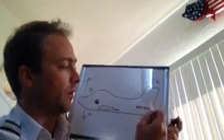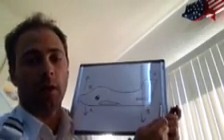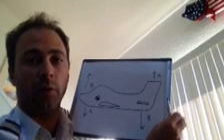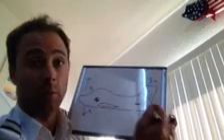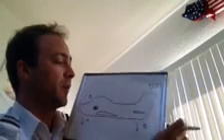So the surface deflected more downward, again it decreases the angle of attack and decreases the lift that the stabilator is producing in the downward motion, of course. So that tail down force is lessened, and the indication the pilot gets, which would have been the nose up, is also lessened. So now our force A and force B are equaling each other.